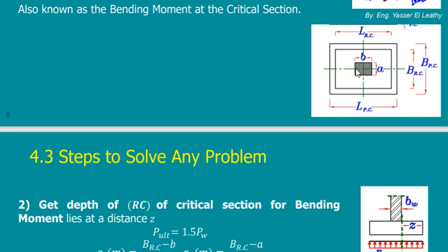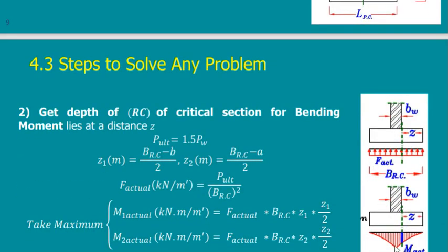It's a foundation with the column, a different case, and it will be very safe because the column increases the stiffness and the rigidity of this section. It includes reinforcement and many things. So the critical section is the section at the edge of the column. So instead of using this bending moment here, please calculate it here. It will be less, and less means less money.